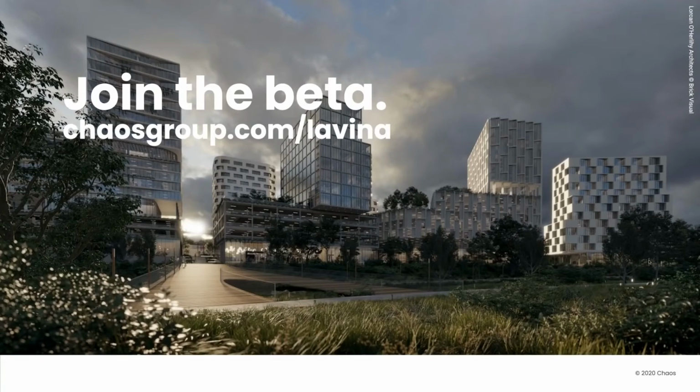And again, we're talking about production quality. You can speed up the rendering if, for example, you want to make just a quick previs. You can tune up the denoiser and limit the rendering per frame to, let's say, 10 seconds, and you will get somewhat decent images, of course, heavily denoised ones. But you will get the quality that I got during the webinar demonstration because it was rendering just for a few milliseconds.